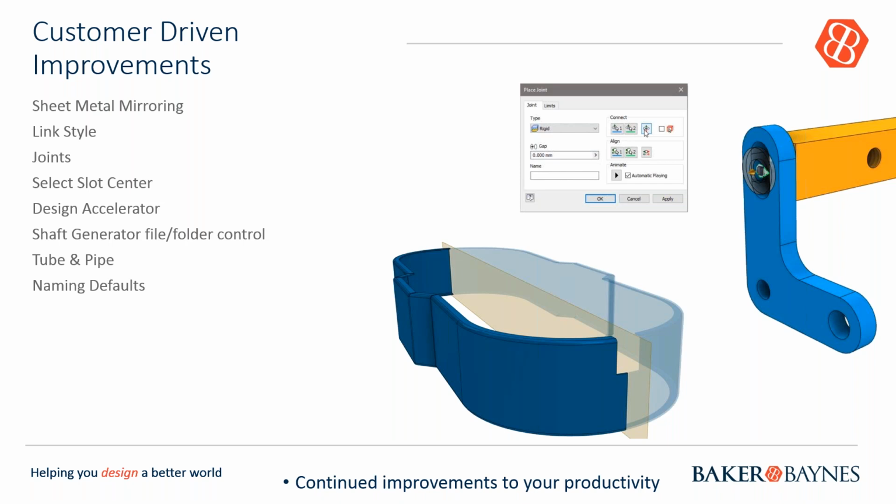The tube and pipe enhancement: the application options in the file tab, file naming dialog box now includes tube and pipe, where you can specify how tube and pipe creates files and folders. For example, you can use these settings to keep a folder structure flat and completely eliminate the API subdirectory. In addition, you can now configure a naming scheme using the options in the new add attribute drop-down list, as we've seen in the frame generator. Okay, design accelerators. The shaft component generator dialog box now includes a toggle that allows you to specify how files and folders for shaft components are created.